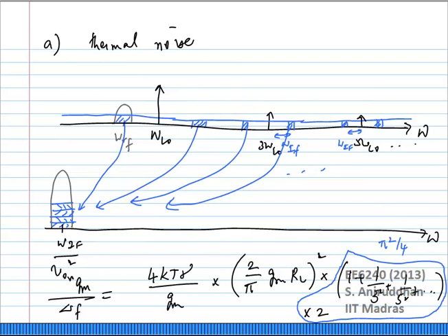The big difference is that the RF signal itself was narrow band, therefore it was available only in a small range of frequencies, whereas thermal noise is actually broadband, so you do have it at many other frequencies. Fundamentally, apart from thermal noise at the RF frequency going to the IF frequency, just as you would see for an RF signal, you also have noise from the image band.